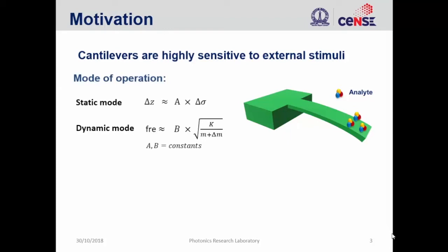One is the deflection, or static mode, where an absorbed molecule will cause a change in the surface stress, and what we see at the cantilever is a change in the deflection or the initial position. And the other is the mass loading effect. An absorbed molecule will cause some change in the mass, and the frequency will change accordingly.